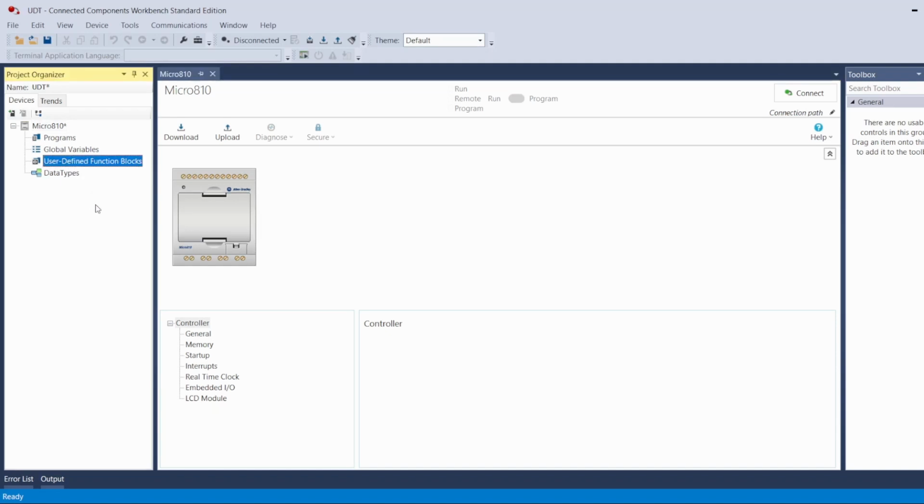First, if you're not familiar at all with the user-defined function block, you have to know what you want and how you're going to control your conveyors. Like, you want to press start for it to start. Before it starts, do you want to check to make sure the safety circuit is good? In my case, I want to make sure the conveyor next to the current conveyor is on first. We need to know all this, and then you will know what tags you need to put inside this user-defined function.